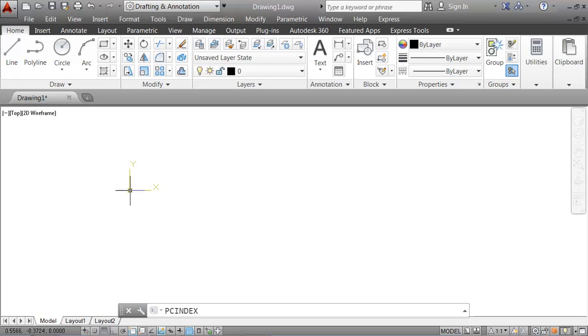If you don't want the line to be connected to the UCS, you need to start with some other value like 50 or 10 or 20, 5 from x and 25 from y. Let's do it from 0, 0 first, and then let's do it from another value. If you click the line command, right, but don't click anywhere, it says specify the first point.